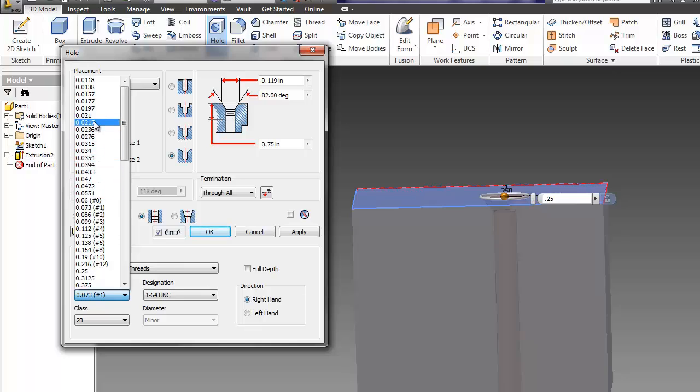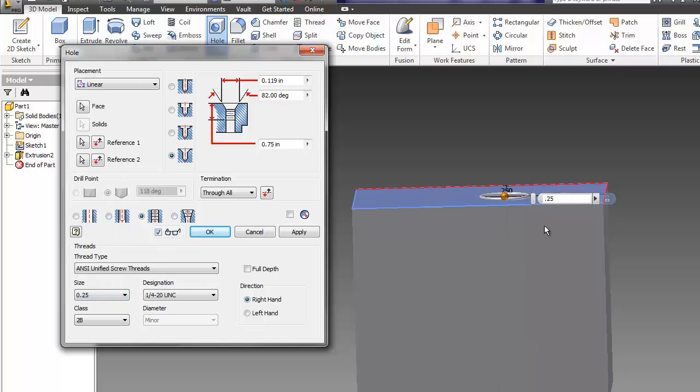So say we did a 1/4 inch, 0.25. Okay, so we get something like that. The tapped hole, class 2B, 3B, 1B. So make an adjustment. It's 2. Alright, and we also have a designation. So the class will be given to you prior to this as well. Whenever you're going to be having to do it, that information will be given.